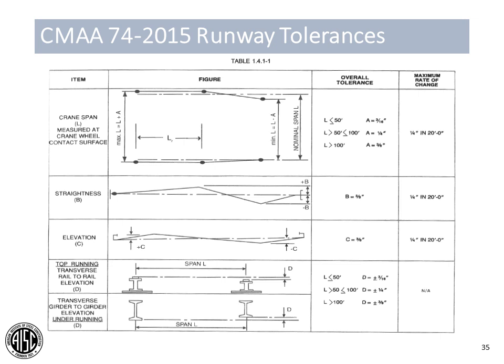So typically the crane manufacturer will specify a maximum gap in the runway surface. A lot of times it's 1/16 of an inch. It's a very, very tight tolerance. That's to avoid binding of the wheel within that gap. That's another reason why the continuous span crane girders are preferred, especially by the crane manufacturers. It's a better running surface.